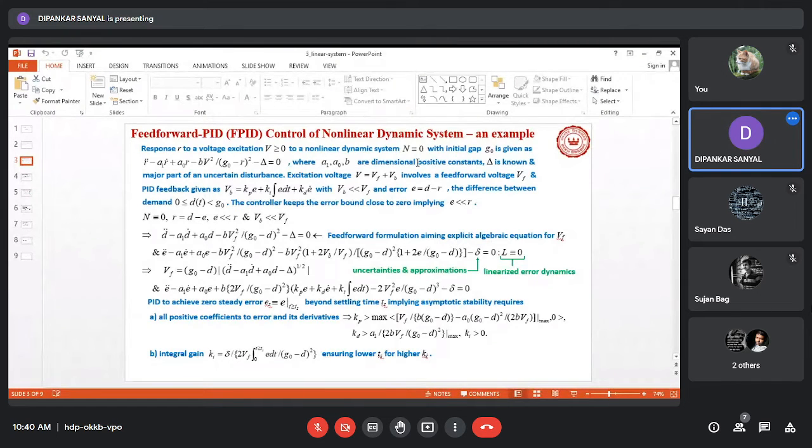But just as we are considering a single representative velocity, that's why we call it a lump analysis. But as you have studied fluid mechanics, you will know that at all the points the velocity will not be constant, especially at the edges where we have the spool land and the sleeve land. There, due to the no slip condition, the velocity will be zero, and in the intermediate region there will be a variation. So that is the actual variation.